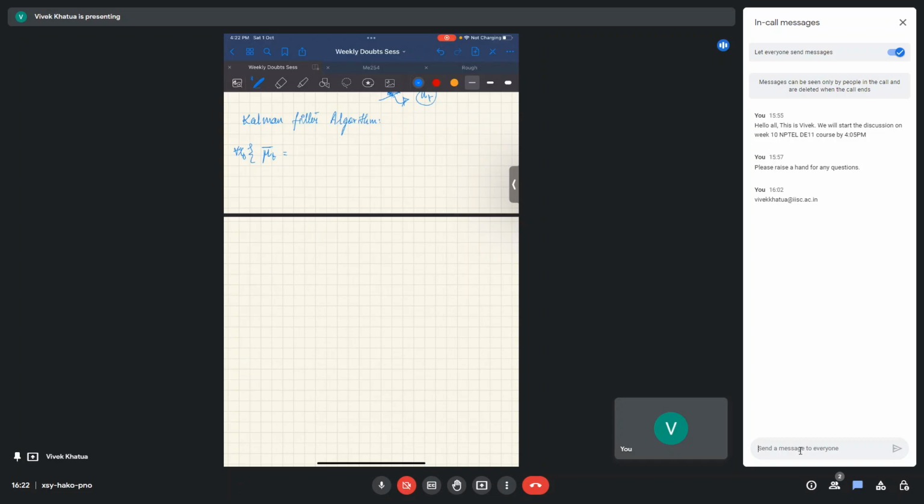Mu t will be the actual state it is in, or the belief that we have that it is in that state, and mu bar is the prediction or estimate that we are making, based on the previous control signal and control input and the state, of what the new state is. That is nothing but the linear state that we have discussed. My mistake, I put x, it's mu t minus 1. So here there is no bar, please note, Bt ut.